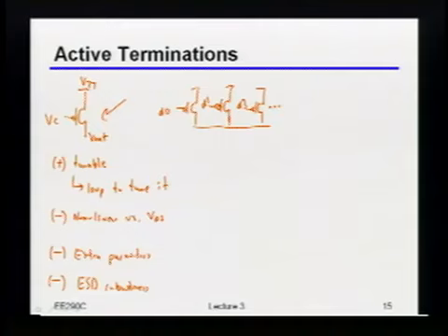There's one minor, let's say, difference here, which is that in the digital version, I can really switch the gate all the way from VDD to ground, right? That means that I can really try and put this thing as far into the linear region as I possibly can. Whereas with something like this, there's going to be process corners where that VC will not really be down at ground, right? And so from a linearity standpoint, it will be more challenging to actually hit the linearity you want, okay?